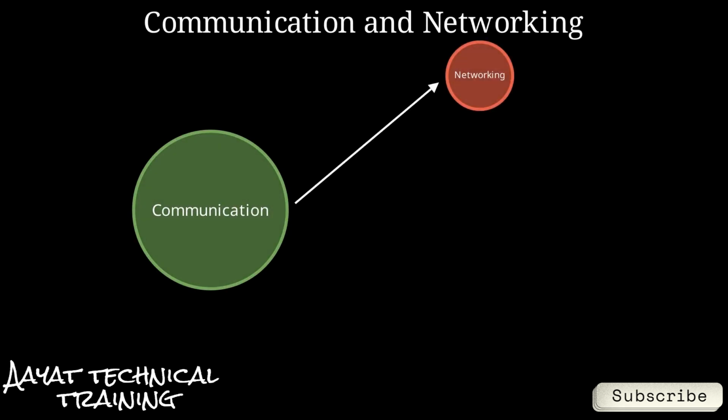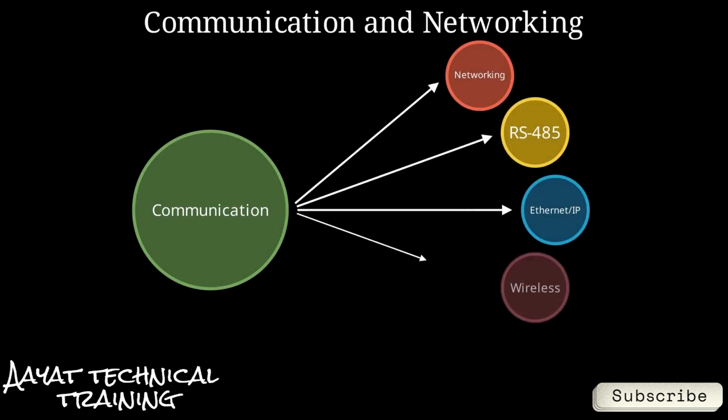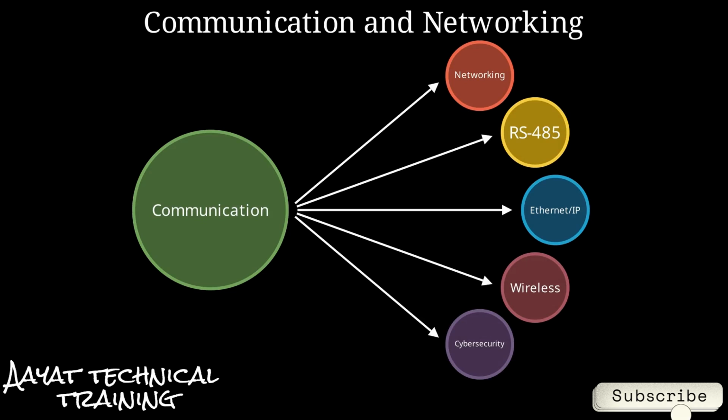Controllers communicate using various protocols and media, including RS-485, BACnet MSTP, Modbus RTU, Ethernet, IP, BACnet IP, Modbus TCP, and wireless options. Some controllers offer dual ports, failover support, and cybersecurity features for reliable and secure operation.